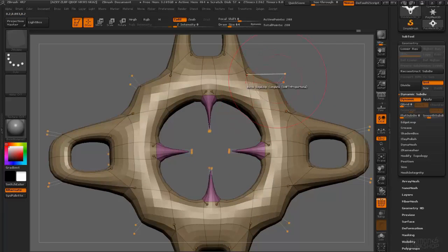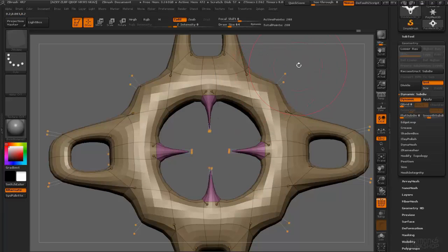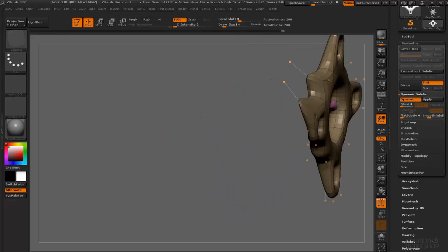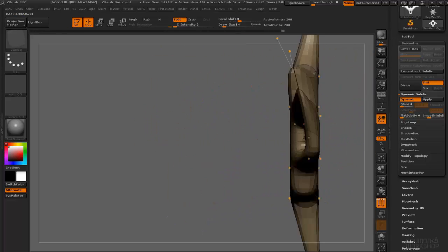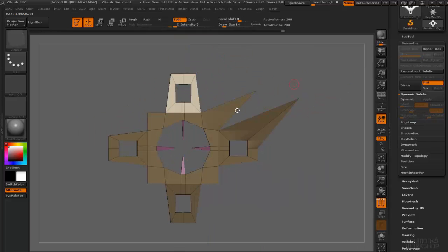So you're also going to have access here to these points, and these are really handy, and they're probably quite recognizable to anyone who's done subdivision modeling before. These just represent the points of the mesh. If I were to push and pull these around, I can drastically change the shape of the model while I'm in smooth mode. If I turn off my smooth preview with Shift D, you can see those correspond to the points of the mesh.